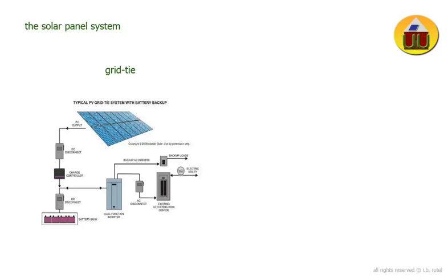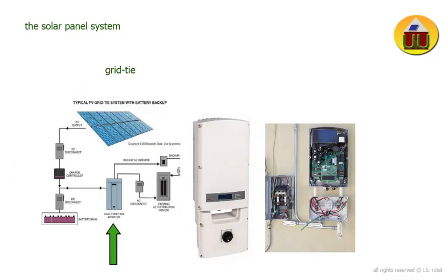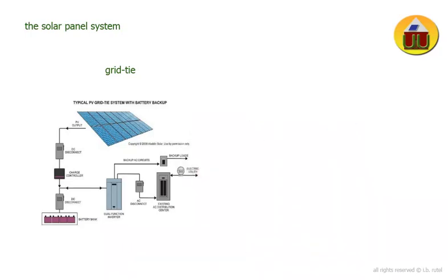But let's take a quick step back and talk about the components in the system. The panels are connected through a direct current system. The direct current, or DC, is like a battery where the voltage is constant. It goes through some safety components like disconnect switches and surge protectors, and then enters the inverter. The inverter changes the DC to AC, or alternating current, which is the electricity you get out of your wall socket. Here the electricity is also conditioned to meet the requirements of utility production. The inverter then connects to your electrical panel breaker box, where it can then connect to the grid.